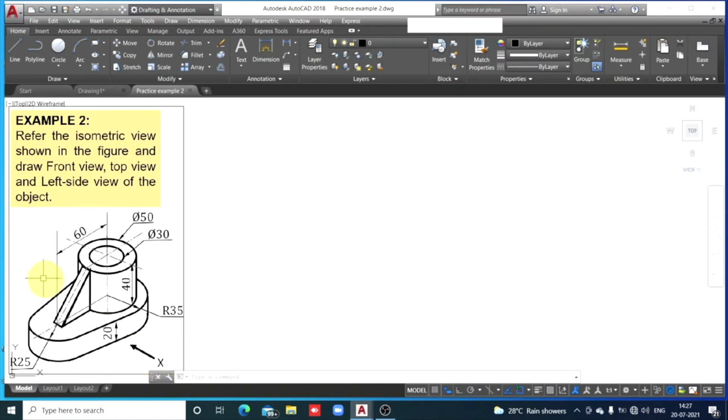Front, in the opposite direction it is back. Then top and bottom. And this is the left side of the object and this is the right side of the object. Okay, so left side and right side are curved edges and center to center distance is 60. So you should start with curved edges. So the left side curved edge, at a distance of 25 millimeters, has its center.